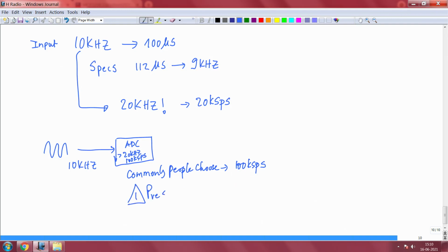Please look up the prescaler, I do not want to diffuse. This is something that you can configure on your ADCs. There is a prescaler value which you can try, and that will essentially change the sampling rate.